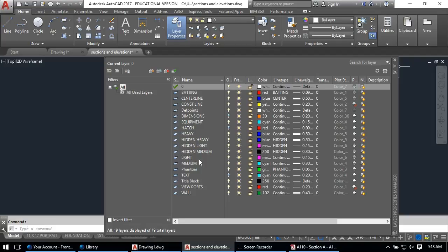Now the other thing that I like to do in drawing sections is if I'm cutting through something but it's internal, say it's a wall composite of something, then the part that's inside, you'll see this when I'm drawing, will be a step down layer. So I might use medium for some of my cuts if it's not an exterior surface. Think of it that way. That'll help with the clarity. So that's what I'll use: my heavy line weight for my exterior surface cuts.